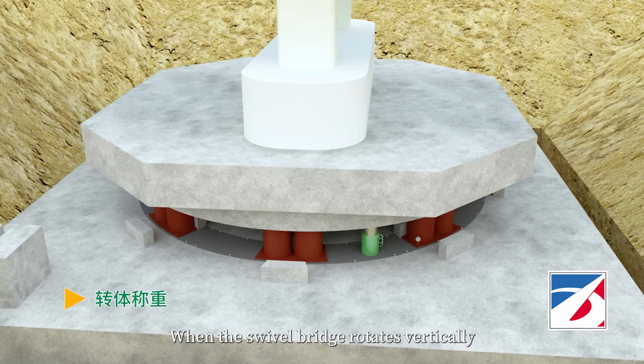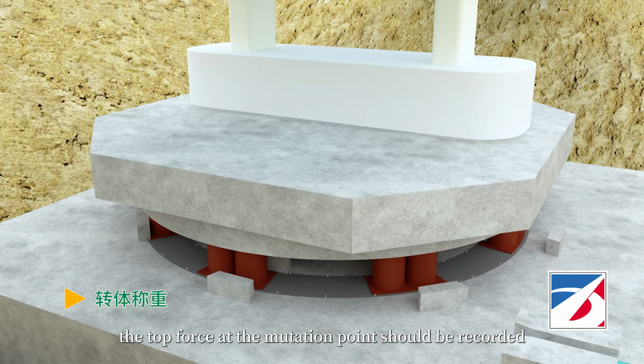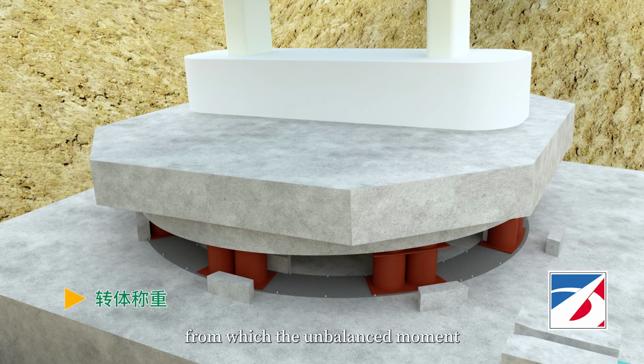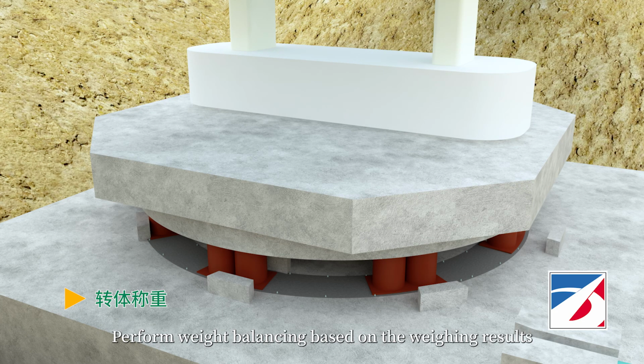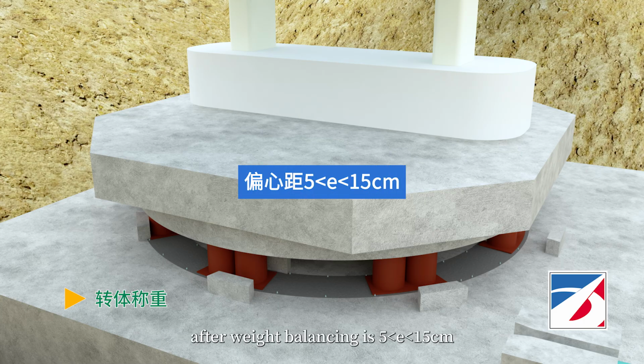When the swivel bridge rotates vertically around the central bearing, the top force at the mutation point should be recorded, from which the unbalanced moment and static friction coefficient of the swivel bridge can be calculated. Perform weight balancing based on the weighing results to ensure that the eccentricity of the swivel bridge after weighing balancing is 5 to 15 centimeters.